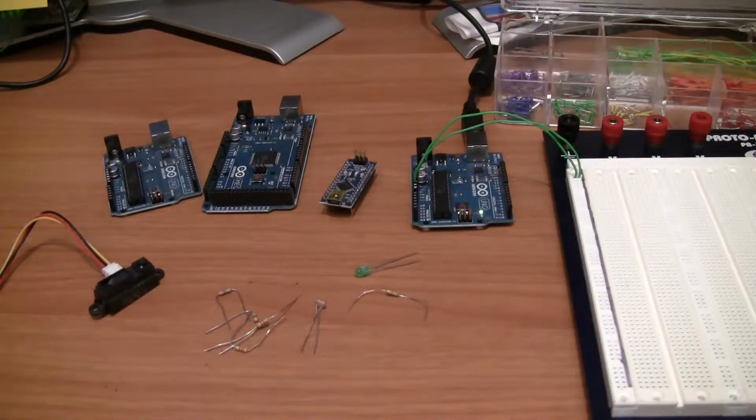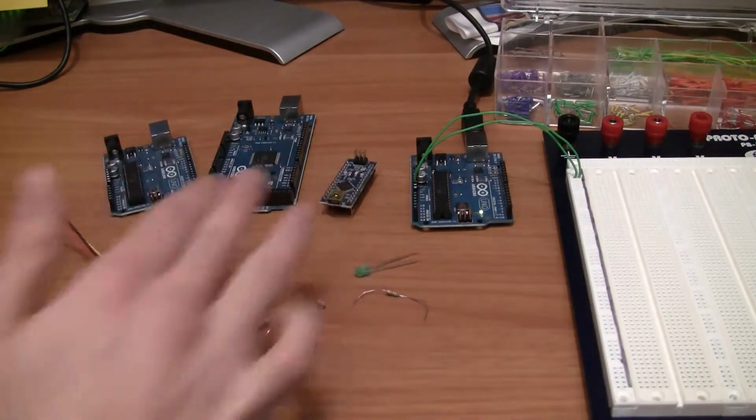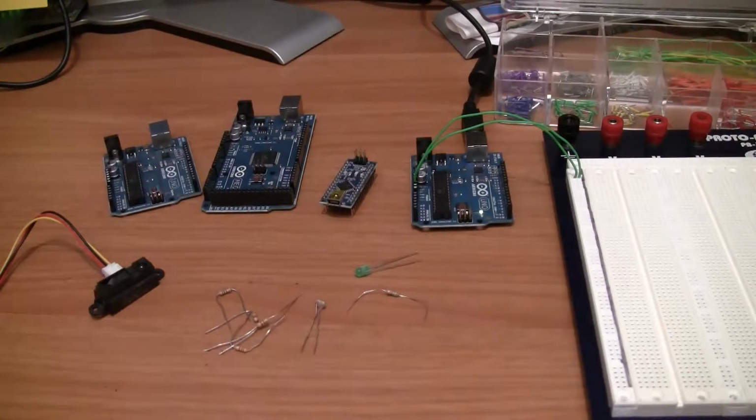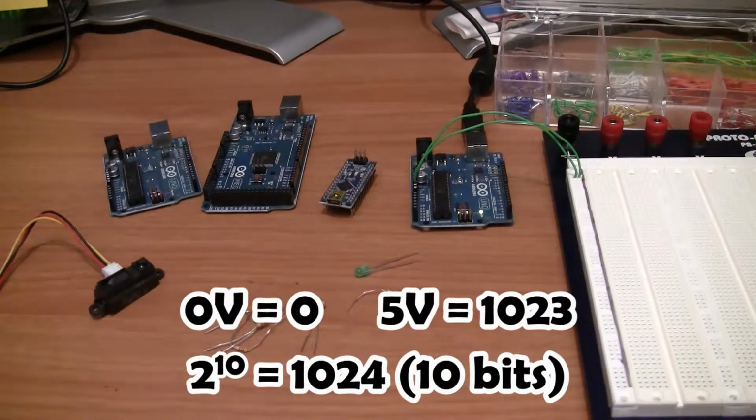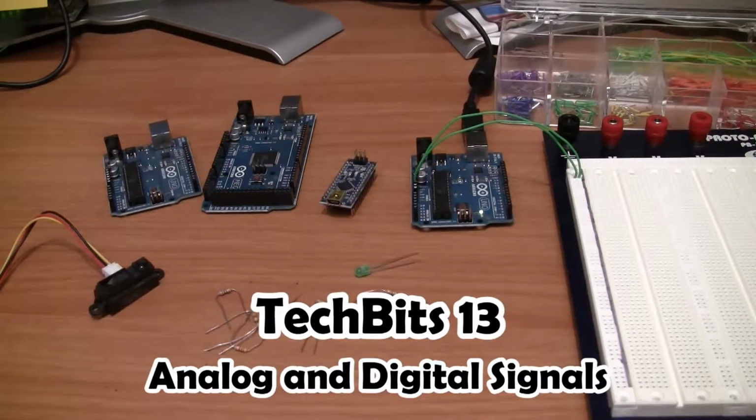So let's get started. Let's talk a little bit about how analog inputs are set up on the Arduino boards. Here I have the Uno, the Mega 2560, and the Nano boards. All of these allow for analog input options, and on all Arduinos there is a 10-bit analog digital converter that allows you to convert from ground up to the input voltage of the Arduino, usually 5 volts, to a value from 0 to 1023. That means you have 1024 bits of resolution, or 2 to the 10th power, hence why it's called 10-bit resolution. If you want to learn a little bit more about how analog digital converters work, please watch my TechBits episode on analog and digital signals.